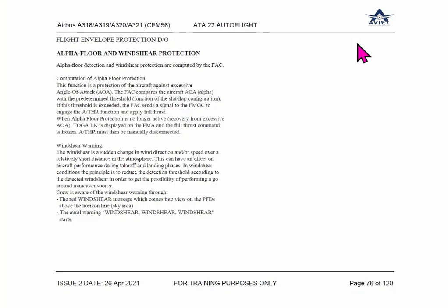Understand this operation. Let's say the aircraft is flying with manual thrust, with the lever wherever it may be. Let us say the lever is at the climb detent. Do you remember all the detents on the thrust lever? Idle, climb, flex MCT together, and TOGA. Four detents are in the forward section: idle, climb, third is flex MCT, and fourth is TOGA.